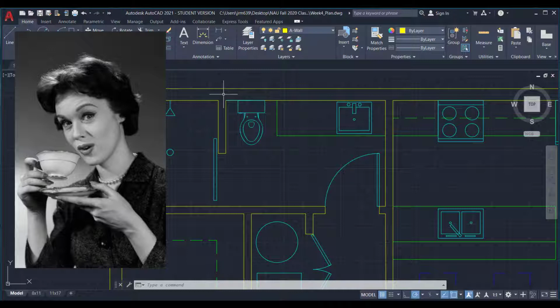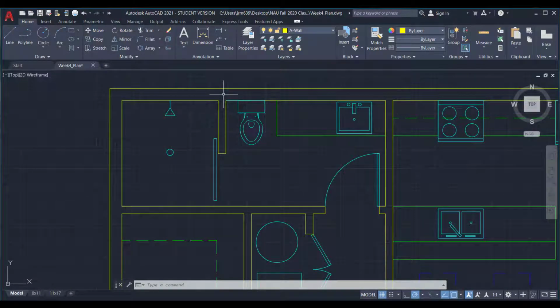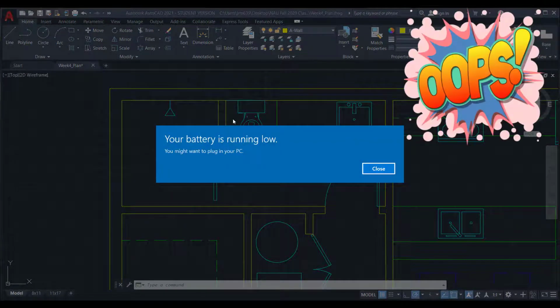And even though there really isn't any right or wrong, there are still things that our field does that you should be aware of. And one of those things is to never draw lines separating walls from other walls. There is one and only time that you actually do draw a line that will look something like this. And that is when one wall is lower in height than another wall. That line separation will communicate to a contractor, hey, something's going on here. You need to understand why this wall and this wall are different from each other.